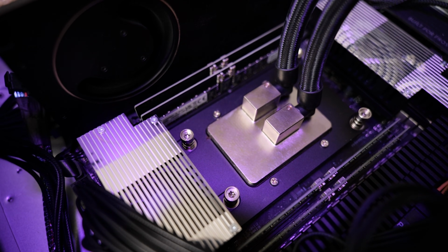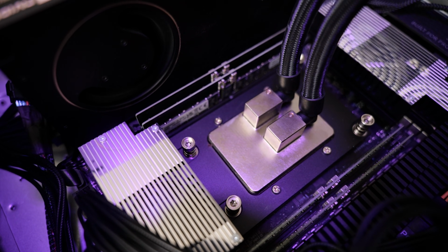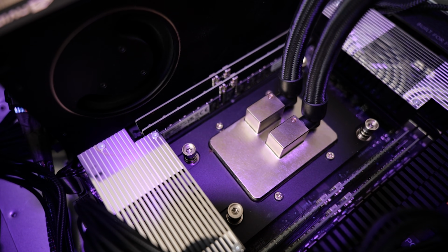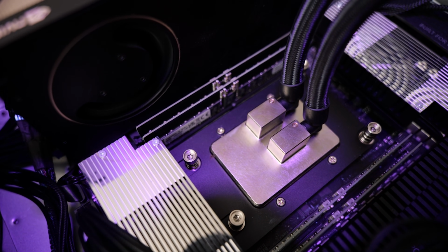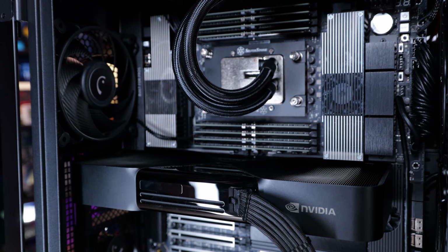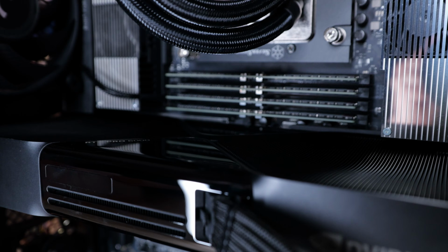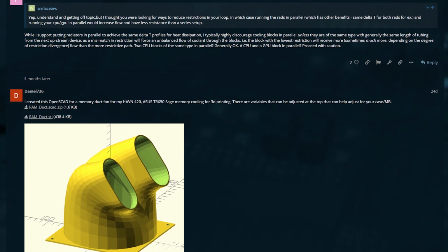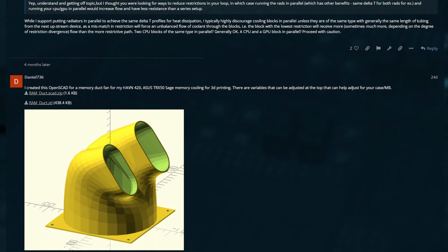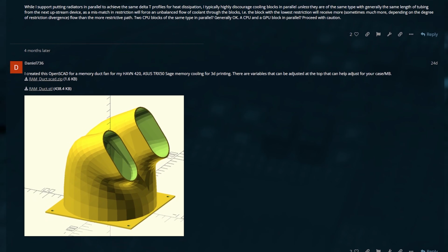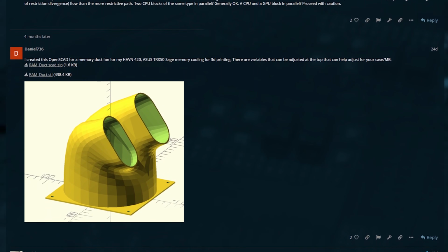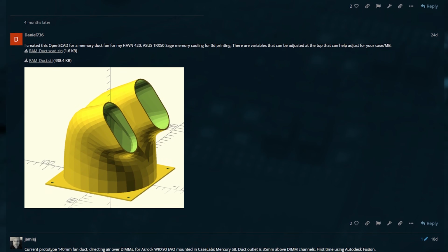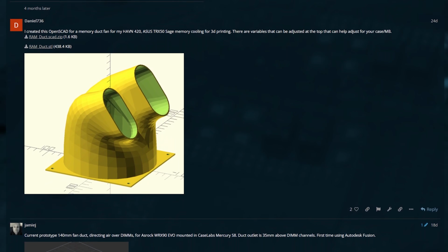So bottom line, Falcon Northwest found a lot of the same kind of things that I did, which is like, well, in this configuration with heat spreaders and this application, it does actually make sense. And so their QC team reached out and I confirmed with them that, yeah, this is actually a problem on ASUS boards. Go Falcon Northwest. And that's also part of why we have the forum thread that has 3D printable options, like some of these brackets that I have here and some that Kelt at Falcon Northwest made out of aluminum, improving the airflow over the DIMMs.